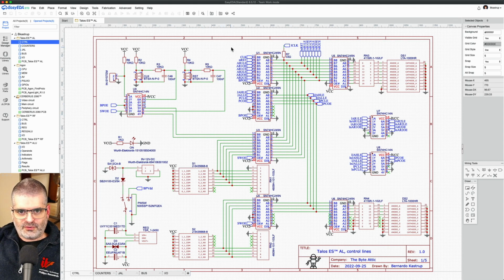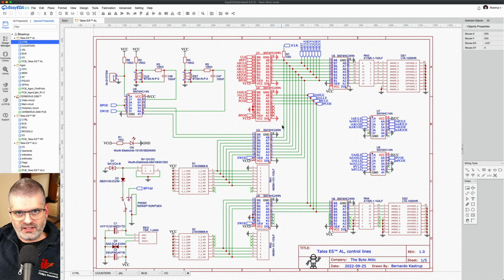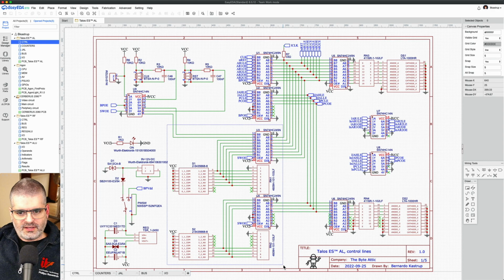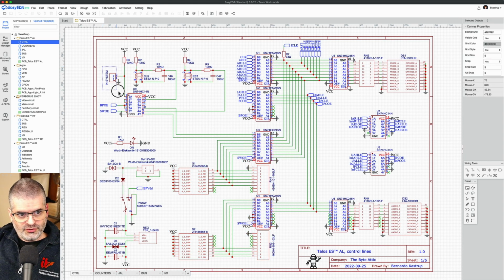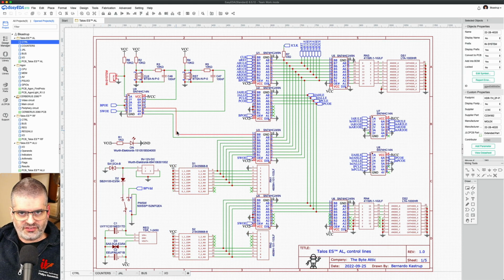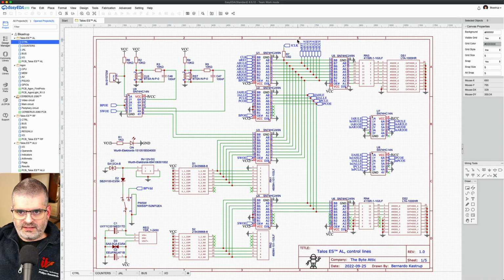And just as before, there are two sets of inputs for the control signals. These come from the backplane connector. They are used when the card is inserted in the system and running full speed. And these are the same thing, but now using dip switches to set the control signals. And the dip switches, of course, are used when you are not in system, when there is no shunt on this header and we are basically in standalone mode. Either way, the outputs are here.